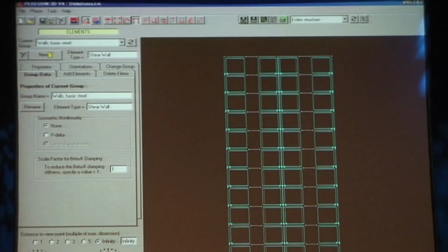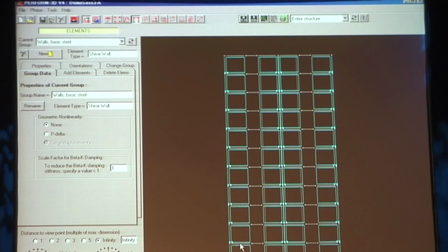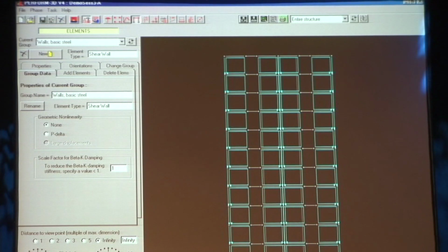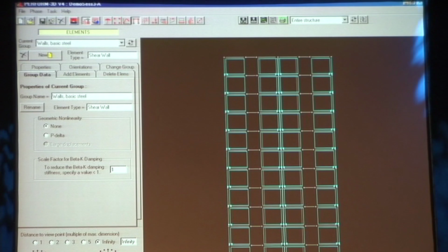And then the other difference was that for the upper beams, I used horizontal embedded beams. For the lower beam, this is a pretty deep beam, I used a vertical beam to connect the coupling beam into the wall. But in all cases, I chose to use beams rather than wall elements. And I'm inclined to think, in general, that's something I'd do. You get sort of better control over the behavior if you use beam components for coupling beams rather than wall components. Does that answer your question?